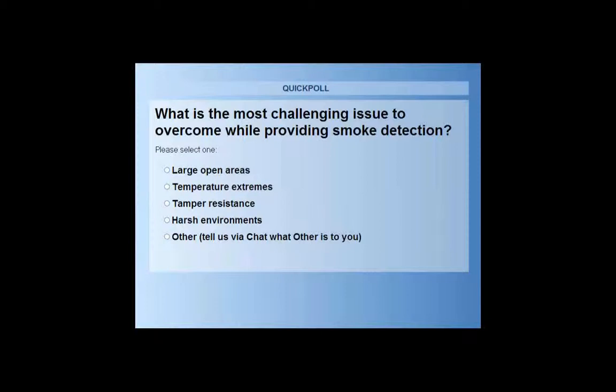The first question that's posted is, what's the difference between early warning and very early warning in terms of smoke detectors? I can answer that. The difference between the early warning and very early warning is the coverage on which a sample port or a spot type detector, if you're designing for that category, is going to cover. So for early warning, it's a 400 square foot spacing for a sample hole, and for very early warning, it's a 200 square foot spacing.